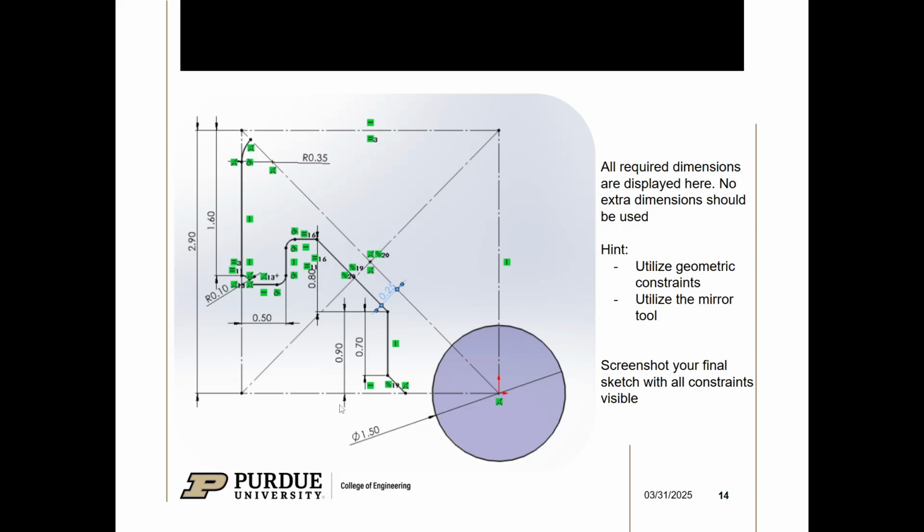You can see here, this was made in another program, so you don't cheat off me. But basically, you can see there are these dashed lines, just like in Fusion. These are all construction lines, right? So you can see I'm basically making a portion of the profile, and then I'm going to mirror it, and then circular pattern it, right?